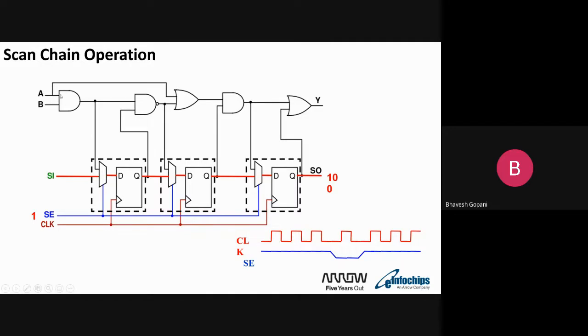Normally in the actual functional mode of this chip, our data is continuously changing based on whatever functional operation is happening. If there is no stuck-at fault, but my gate is somehow slow, or my interconnect length adds more delay, it is basically a kind of delay testing.